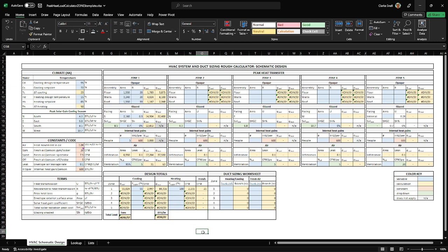And if you don't get some of these things, you can just fill in the chart and get outputs and then try to figure out what's going on. Okay, so then from there, if we were just talking about this one zone, we would keep going. We'd say, okay, now I know that in this case my heating load is going to drive my duct sizing. And so how big a duct do I need? I'm now going to use that